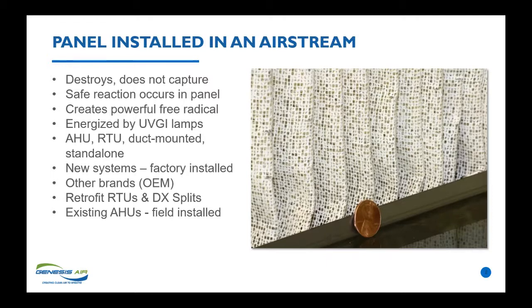But in an era where indoor air quality is no longer value engineered out of a job, there are DX splits for things like residential systems or commercial systems that basically use glorified residential equipment. This is a product, because of the low static pressure drop, that you can utilize where you can't put medical grade HEPA filters in. So remember, whether it's an existing or field installed or new application, PCO panels can go. Let's look at some of them being installed on the next slide.